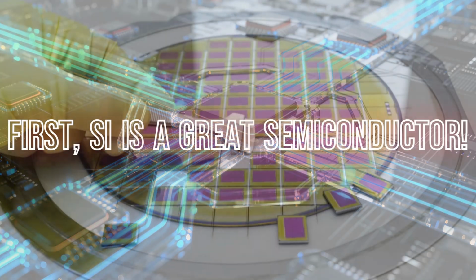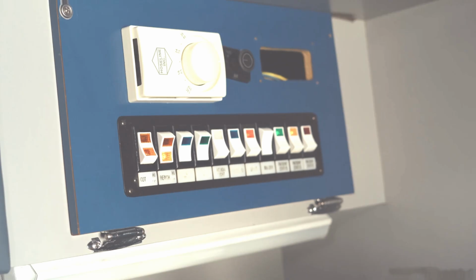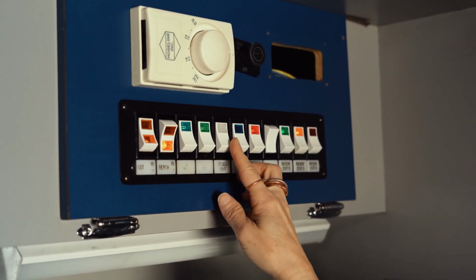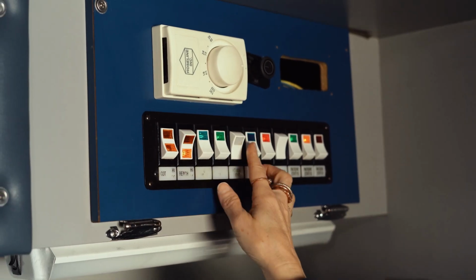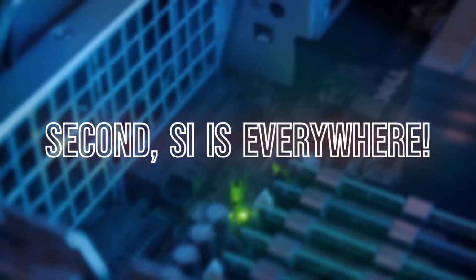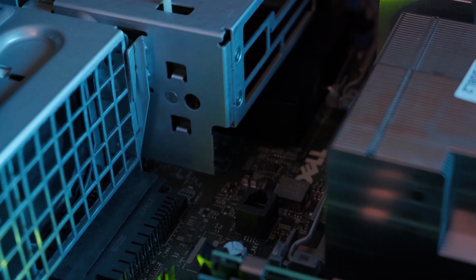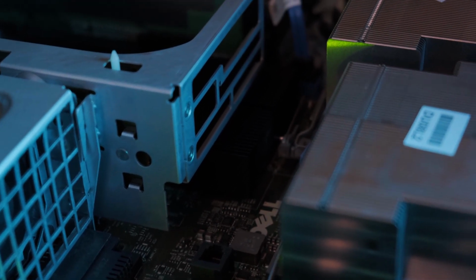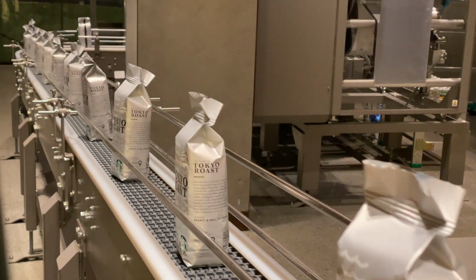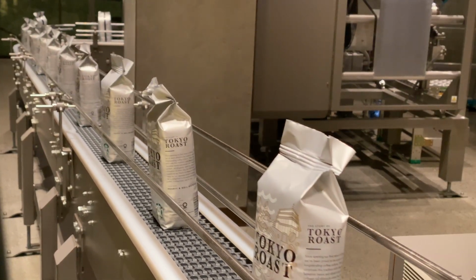First, silicon is a great semiconductor. It has a band gap of about 1.12 eV, which makes it ideal for switching cleanly between the off state and the on state. This is crucial for digital logic, where we want clear, reliable transitions between those two states easily. Second, silicon is everywhere. It's the second most abundant element in the Earth's crust, found in common materials like sand, silicon dioxide. This wide availability keeps raw material costs low and supports mass production at scale, a major reason silicon ICs are so affordable today.